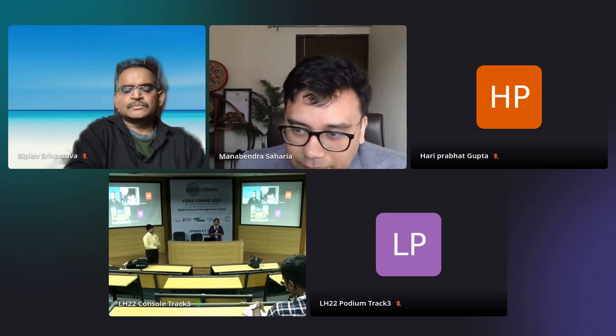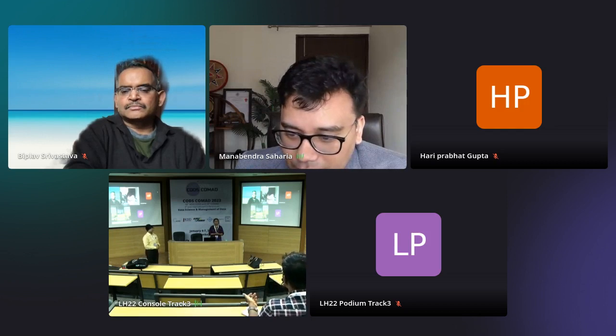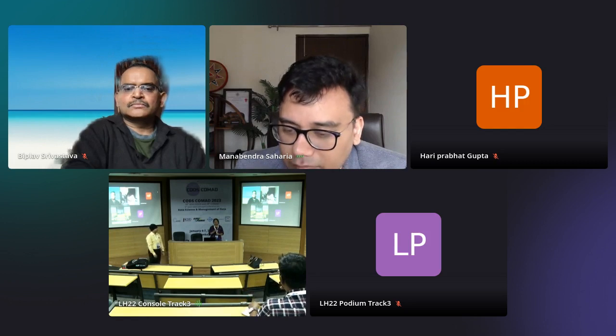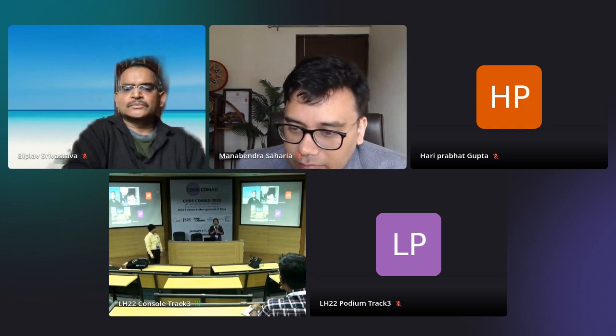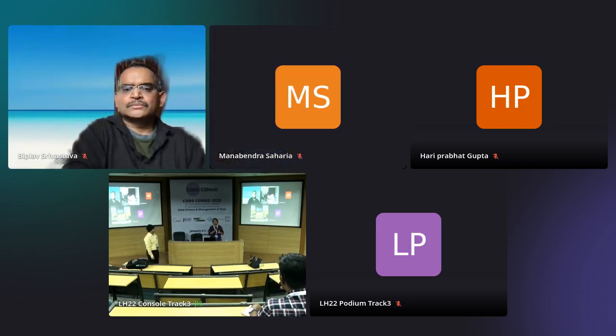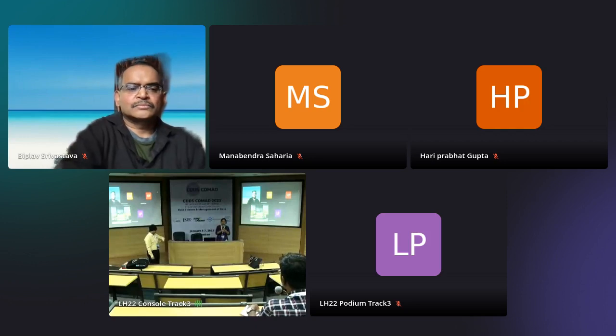My next question is, what are the factors that you consider in the water, like pH level and so on? So there are a set of quality parameters that we look at. The India government mandates certain quality parameters. If you're looking at drinking water, it's going to be a certain set of parameters. Wastewater, something else. You can go to the CPHEEO website to look at drinking water parameters, and you can go to the CPCB website to look at wastewater parameters. I see.